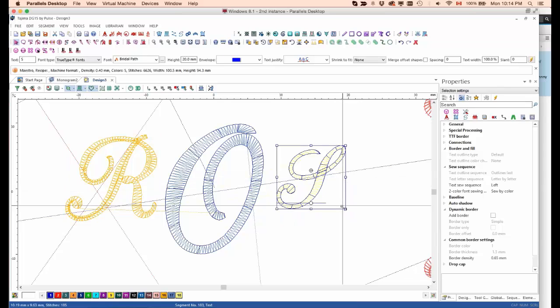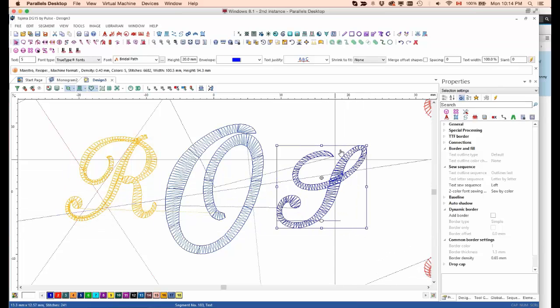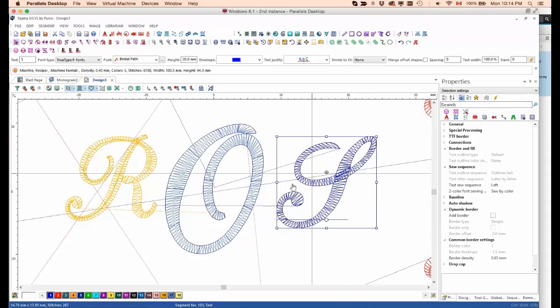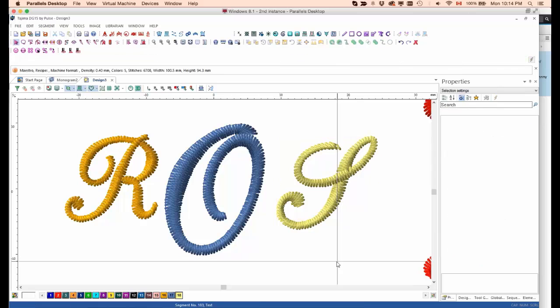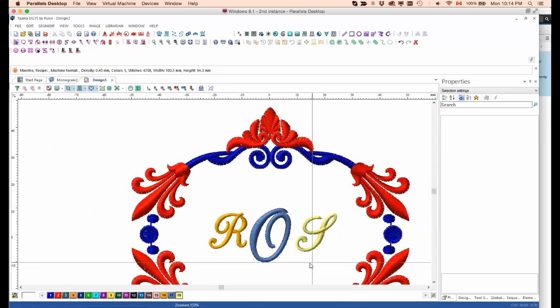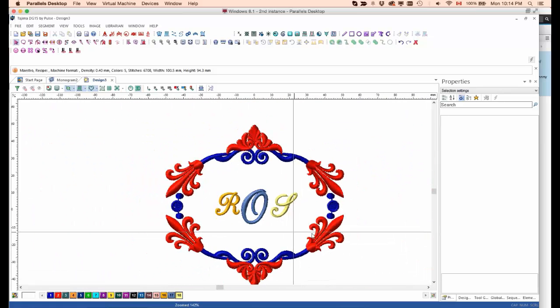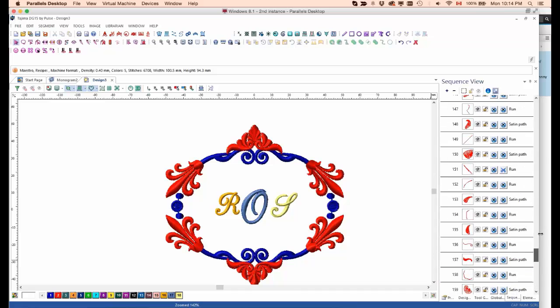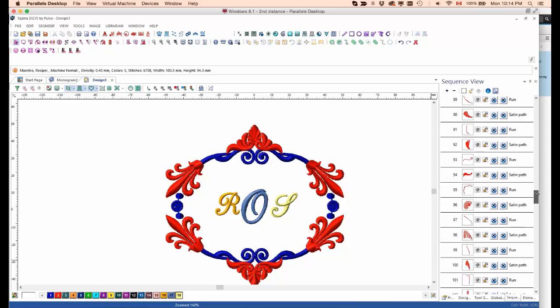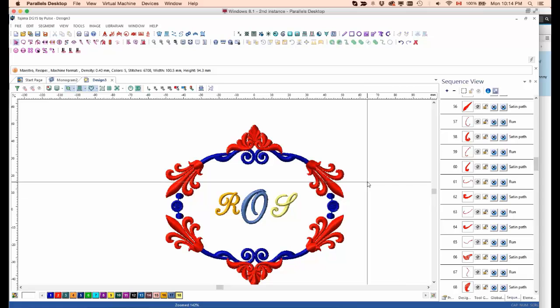The S, let's do the same thing. Resize the S as well, so we come more or less same size like the R, and we'll change that to yellow. Okay, let's hit 3 so we can see in 3D how my modifications are done. So you see here, you can also do, of course, let's go to the sequence view, and here you can see all the segments. So you can do your editing as you are used to it. All right, change colors, change the size of segments, or create groups, and so on and so forth.